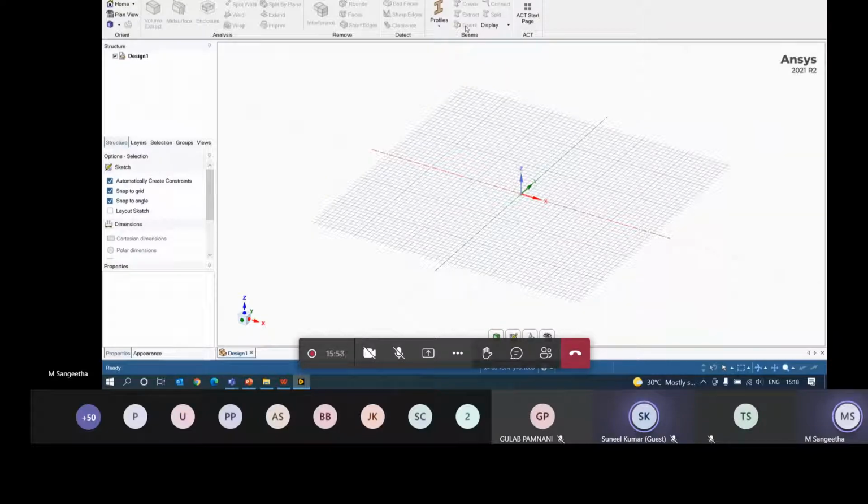And let's say someone is working on some beams problem. Related to beams, there are certain standard libraries existing, out of which you can take those cross sections directly and use them, or you can also extract them from existing 3D models. And you need not worry about connecting those beam models, because you directly have a beam connectivity which will help you in terms of continuity and the load transfer, what we talk about in terms of beams. So that also you can do very easily.